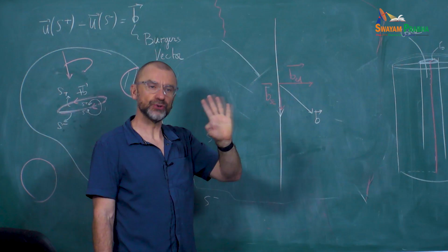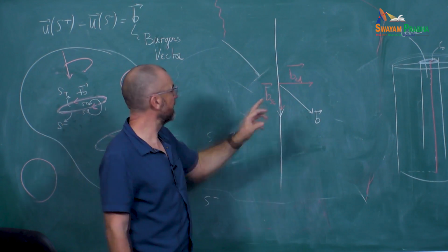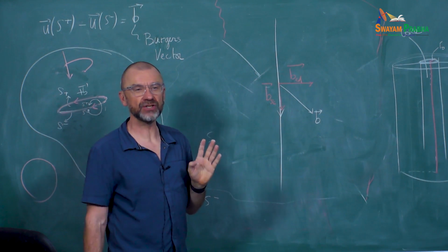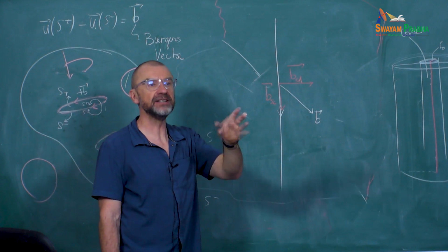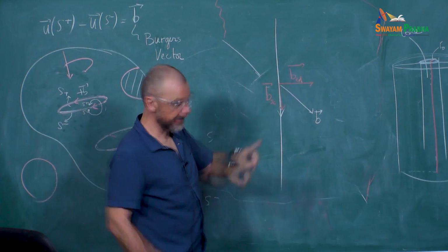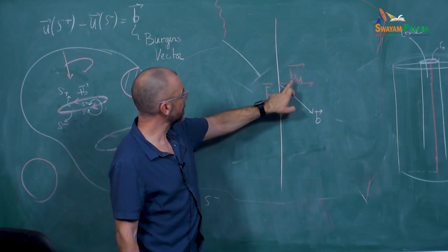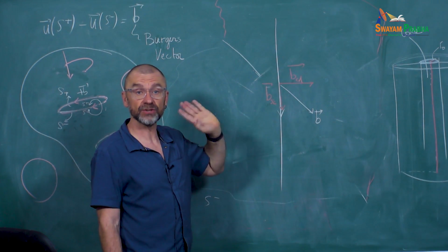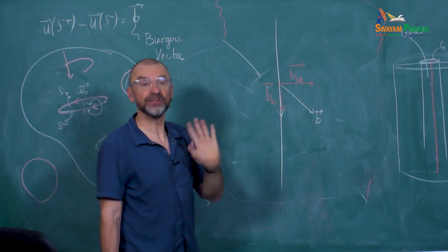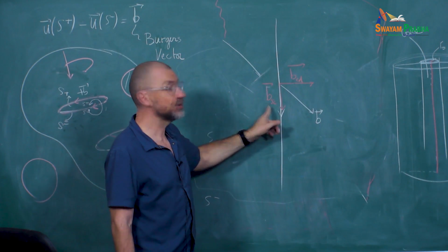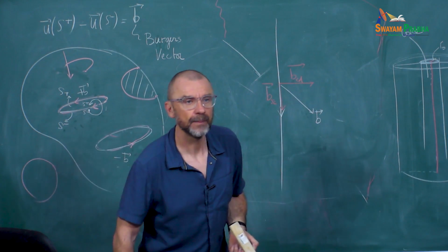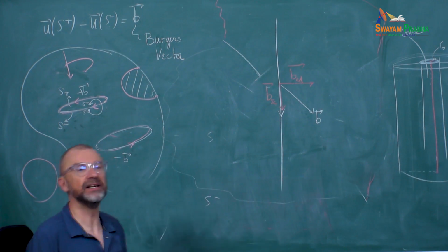Moreover, and you have to show it, if you look at the energy, a superposed screw and edge dislocation do not interact with one another. The integral of sigma times epsilon is 0 when you are looking at the energy of an edge and a screw. So there's no interaction between edge and screw. As a result, the energy of the full dislocation is also the sum of the energy of the edge plus the energy of the screw dislocation. Yes, that is only when the line vectors are parallel. When they're not parallel, then they interact.